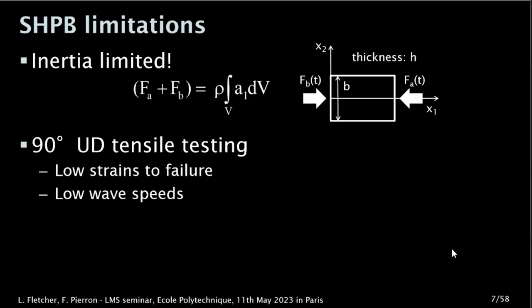So this assumption has drawbacks in particular cases, generally in quasi-brittle materials. These are things that deform very little, and you might reach damage or fracture before you can establish that quasi-static equilibrium. Particularly if you look at carbon epoxy or glass epoxy composites.